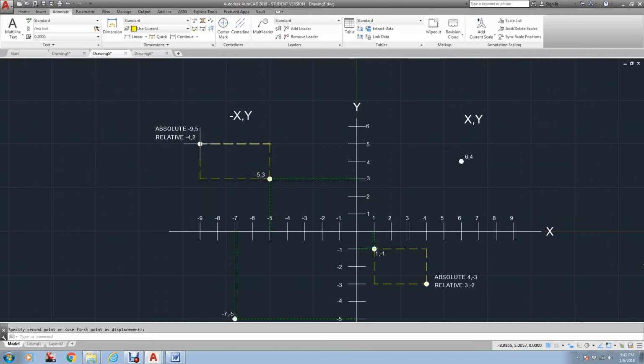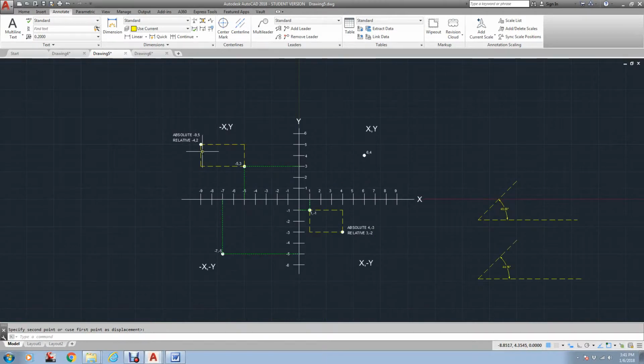Now, the reason I want you to remember these is, if you haven't yet, on the dynamic input, which is right up here on the screen where the cursor goes, any coordinates you input up here, like if I go 5, see the 5 coming up, comma 5, that is relative. When you put them in down here at the bottom under the command line, they are absolute.